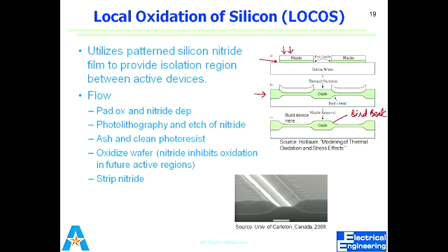If the height of that oxide is too much, it's because the growth is always two-dimensional. It's not growing only in this way, it's also growing in this way. Due to the two-dimensional growth, the height increases in this part, but at the same time it increases this way as well. It goes under the nitride layer.